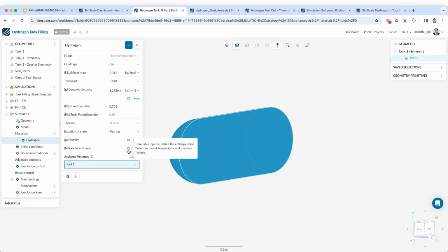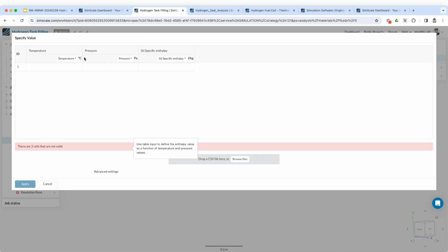Yeah, I think so. And how would you access this real gas table? That question is actually from my side because I think that would help understand better where one could get this real gas data from for specific conditions. Definitely, yeah. So usually there are a lot of databases available, but one such suggestion is the NIST database, where you can plug in the pressure ranges and the temperature ranges that you want to simulate and get out the temperature dependent material properties, which you can upload as a table format here.